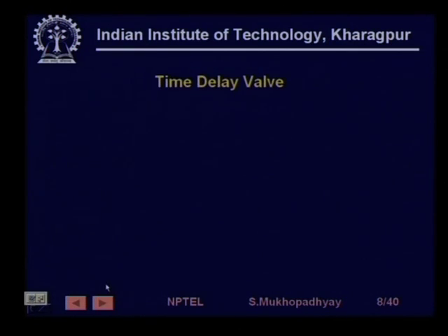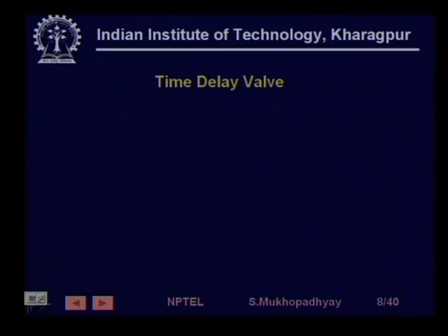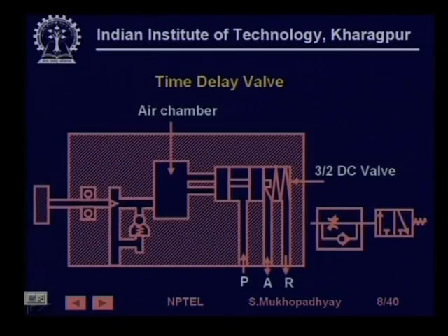Similarly, sometimes you want time delays for synchronization purposes. You would like that after you put an actuator, there are 3 valves which will actually move one after the other. So, if you have to realize this concept of one after the other, then you have to create gradually increasing time delays, after which these valves will be shifted. This is a typical construction.